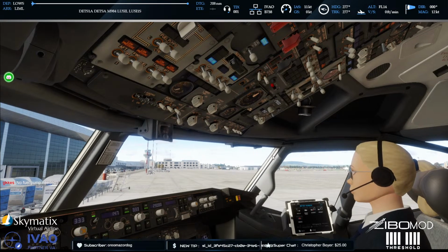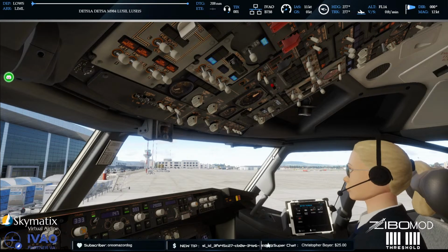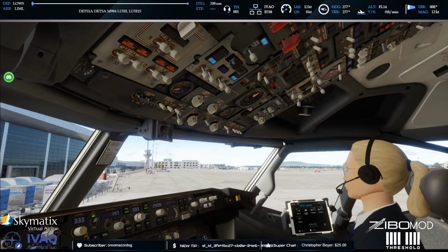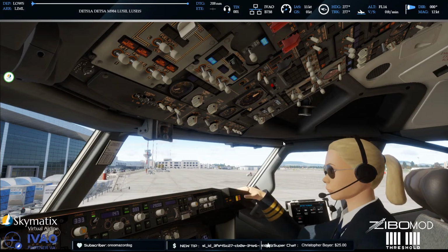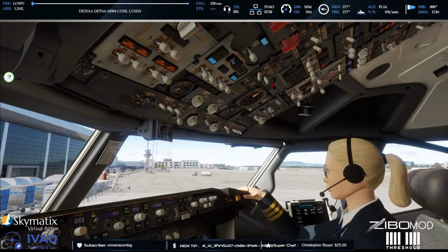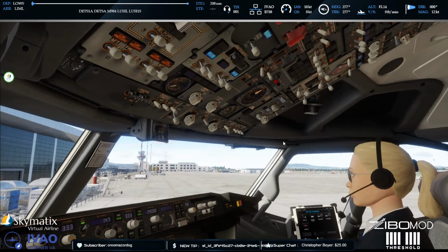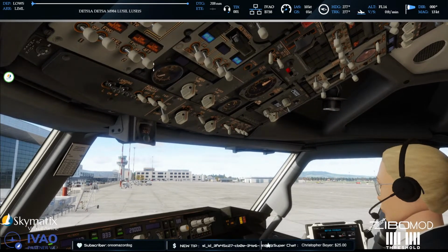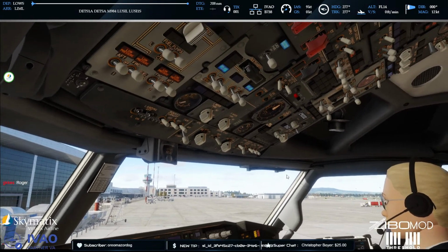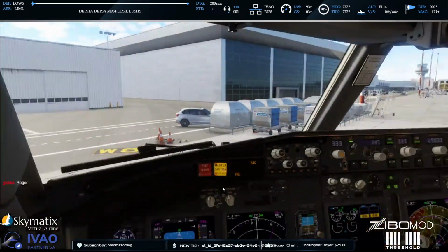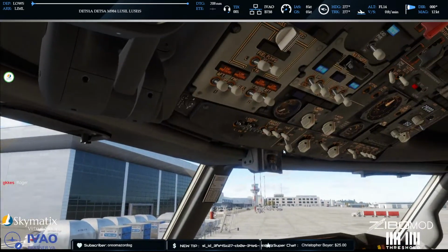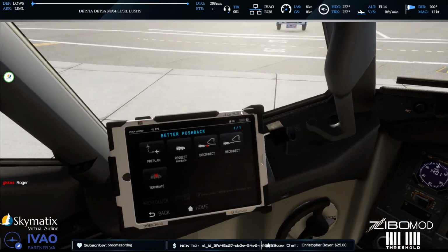No, I was going to say current generations of the APU, you don't need a fuel pump unless you're at high altitude or running extended periods over 30 minutes. If you're going over 30 minutes, that's a problem because wear and tear becomes a problem. The APU's got a built-in fuel pump. The reason the guys use one of these switches is for maintenance and costing purposes. In the real world, they prefer to still use this above the built-in pump, but we're not in the real world, so we're just using that one.